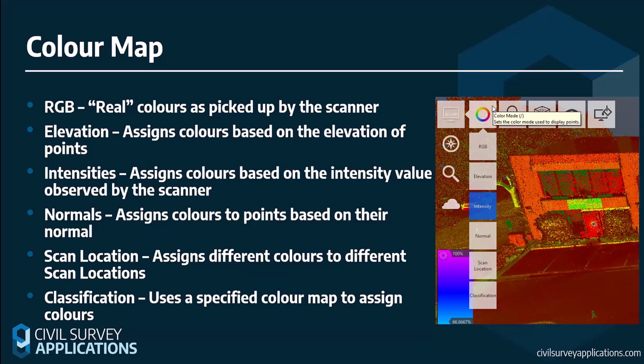And again, classification, allowing you to assign different classifications to your points. And depending on your scanner, this can either be done in the field, and when you've imported, you're able to classify it, or set up your classifications there, or you can manually classify it, or you can automatically classify it. We'll be going through manual classification and automatic classification today. So hopefully everyone looks forward to that.